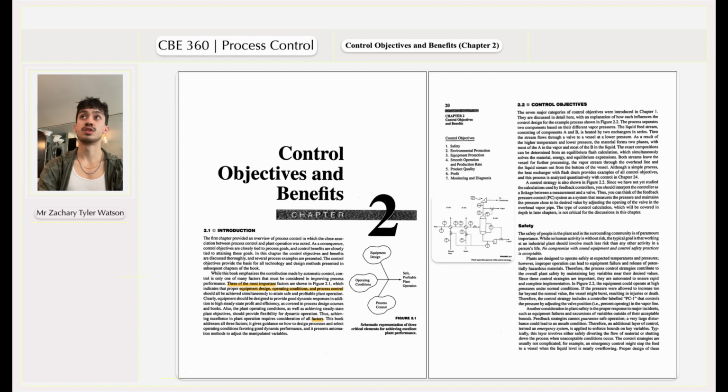Okay, so suppose that the sensor stopped working, providing a reliable measurement. The control strategy could improperly close the overhead valve, leading to an unsafe pressure. I don't think the overhead valve is talking about the safety valve. I think it's talking about the exiting vapor streams valve. So if the pressure controller,